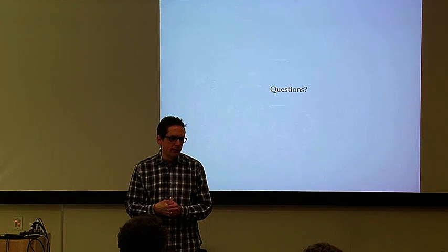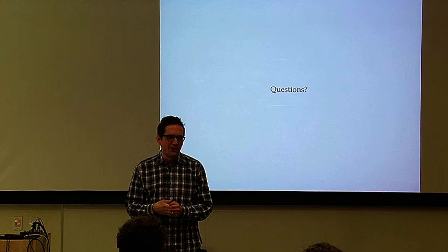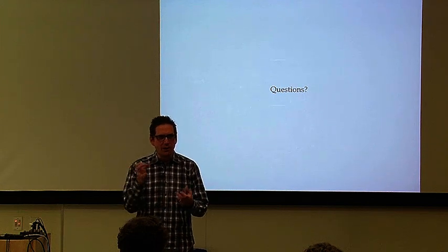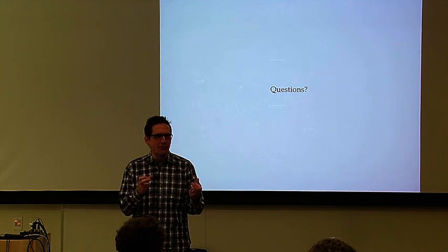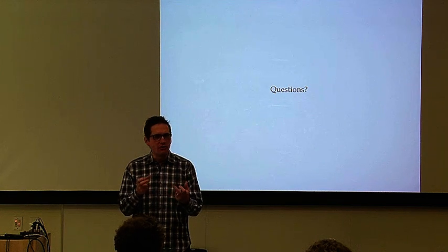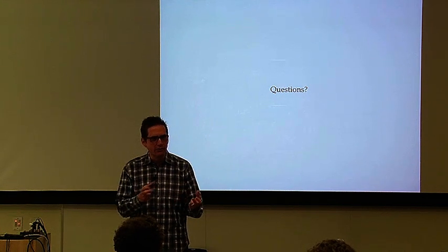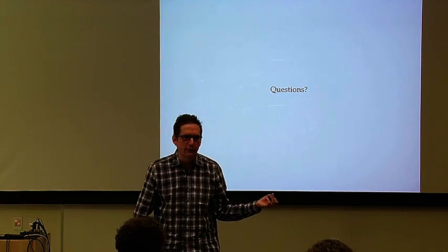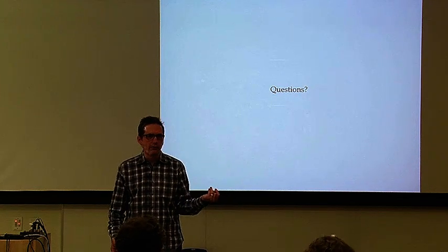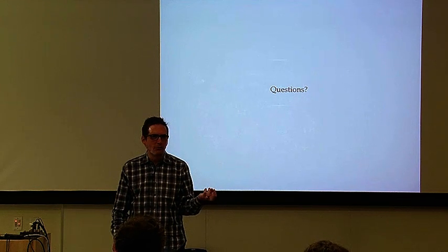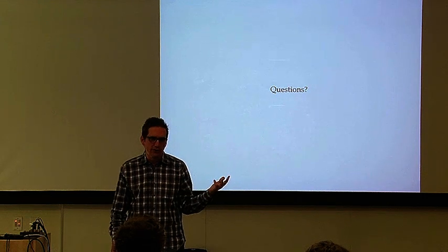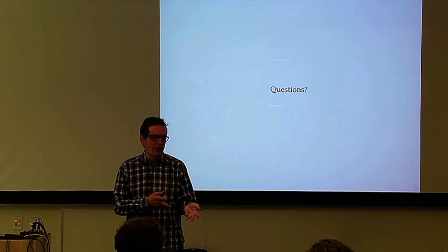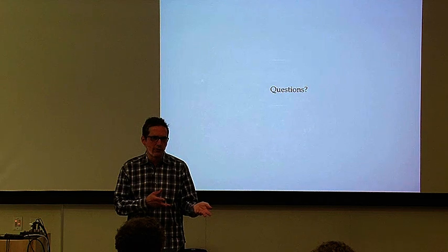Then the next thing for reverb is memory size. So you needed to find a way to connect to memory that's cheap. And what you'll find is each embedded processor supports a different type of memory device. And so you have to do a lot of shopping through Mouser catalogs to find out how much those things actually cost. And so what we found was that this ARM processor costs like $11, and the memory it talks to costs about $4, which was reasonably inexpensive. And of course, all costs get multiplied before they go to the market. But it made it affordable. And what I didn't want to do is make a module that no one could afford.